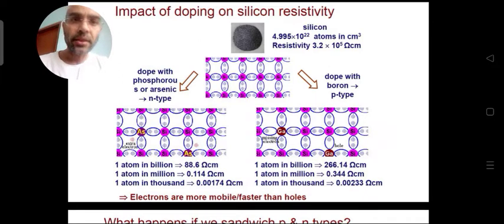So we take a silicon bar. In that silicon bar, if we dope it with trivalent impurities like boron, gallium, then it will form the P-type material. Whereas if you dope it with pentavalent impurities like arsenic, then it will form the N-type material. So in this substrate, you have P-type material and N-type material. By doping, you make this material. In this slide you can see that the P-type material is formed and the N-type material is formed.